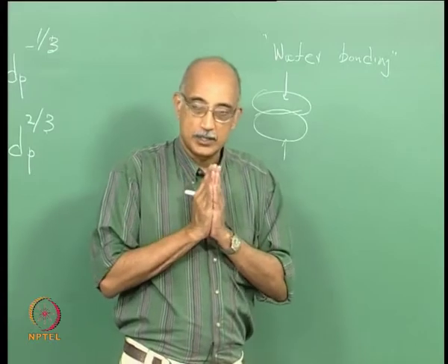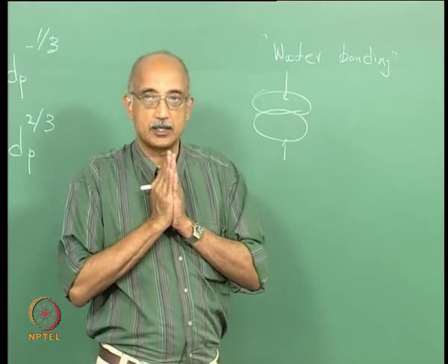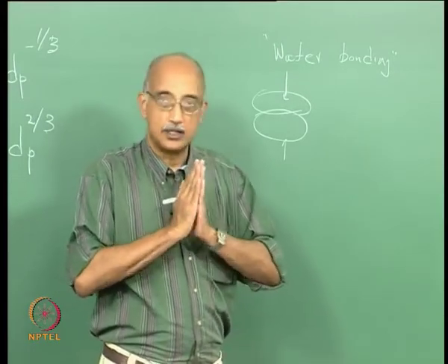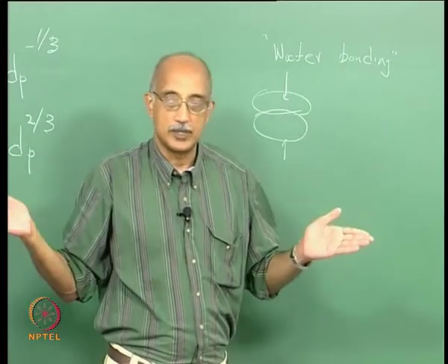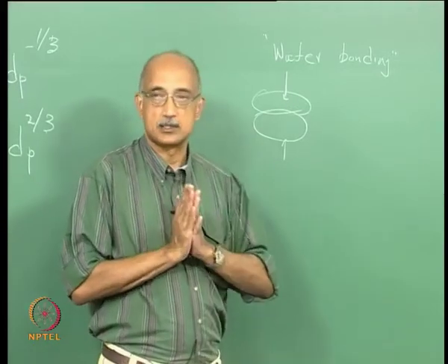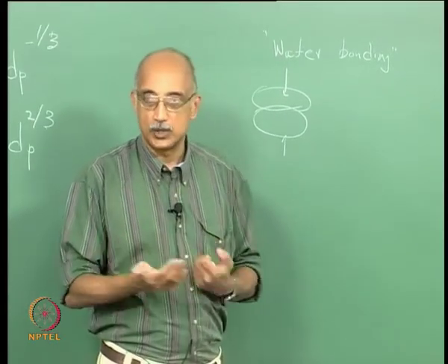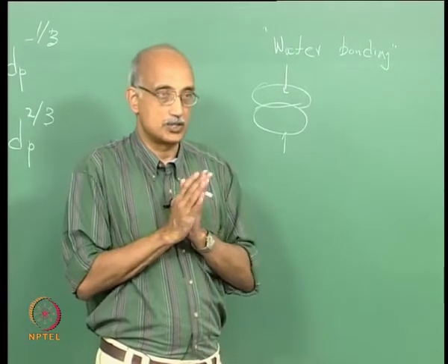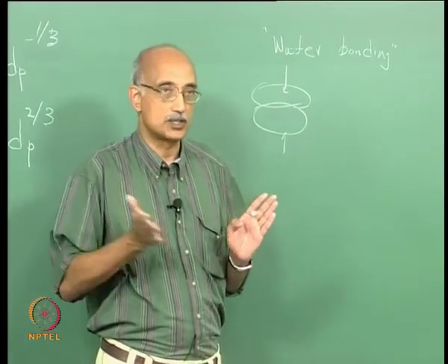There are two reasons. One is that once you have done that, you have essentially sealed these surfaces so that they cannot get contaminated anymore, they cannot get oxidized. I mean, essentially you have hermetically closed these two surfaces. So, you do not have to worry so much about keeping the environment clean and all that. The second advantage is you can now process wafers in pairs instead of one at a time. So, from a processing viewpoint, from a throughput viewpoint, it is advantageous to take pairs of wafers and press their polished sides together through this wafer bonding process and then take them through your process as a pair.